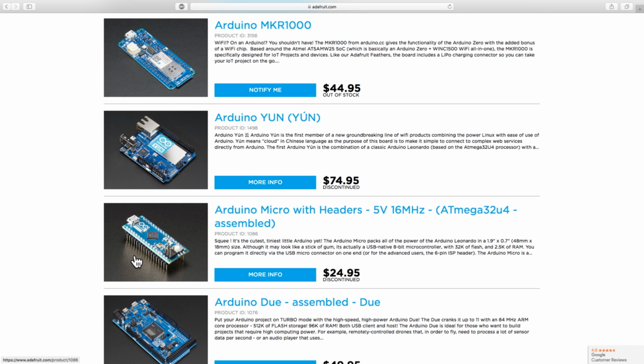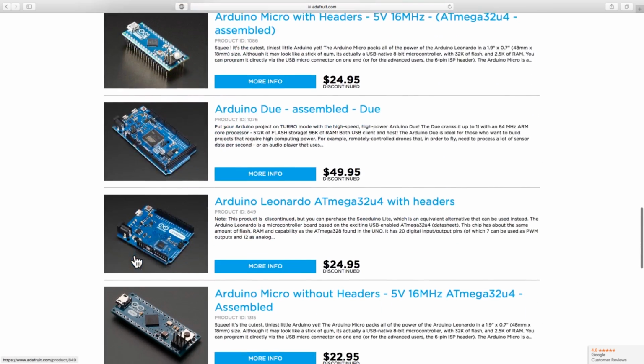What you may find is that when you design your initial product, you use a number of different shields in order to accomplish a task. So you put on, let's say, a Wi-Fi shield. We'll talk about shields in a minute. Then when you go to build 5 or 10 or 50 of the exact same devices, you find you can buy an Arduino board that has the Wi-Fi component already built in. That will save you money, energy consumption, size, and all of that kind of stuff.